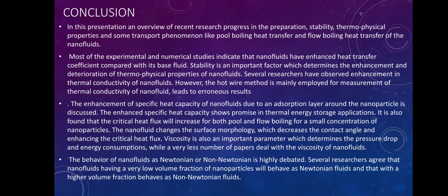Several researchers have observed enhancement in thermal conductivity of nanofluids. However, the hot wire method, which is mainly employed for measurement of thermal conductivity of nanofluids, leads to erroneous results. The enhancement of specific heat capacity of nanofluids due to an absorption layer around the nanoparticle is discussed. The enhanced specific heat capacity shows promise in thermal energy storage applications.